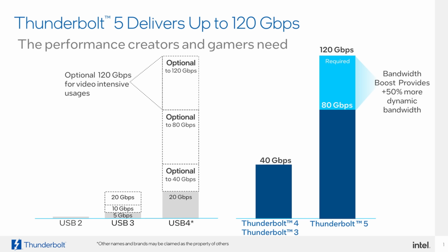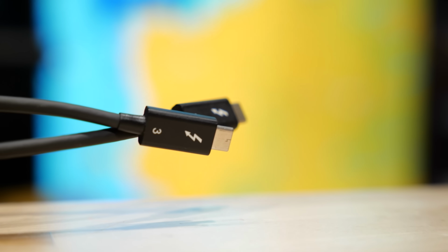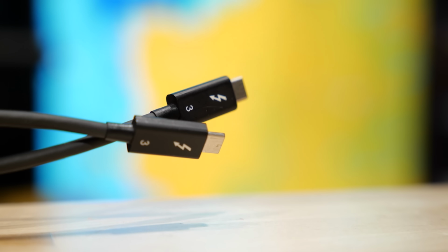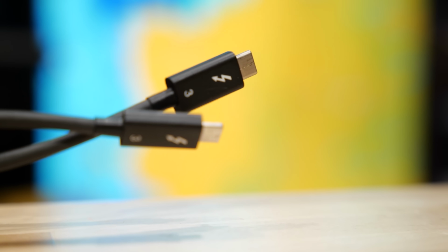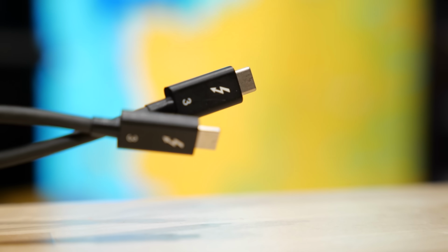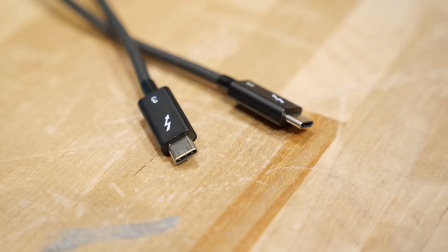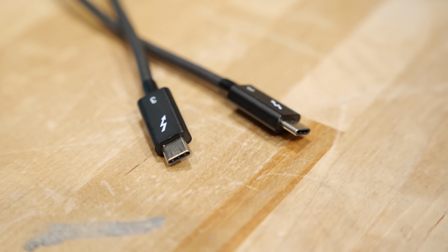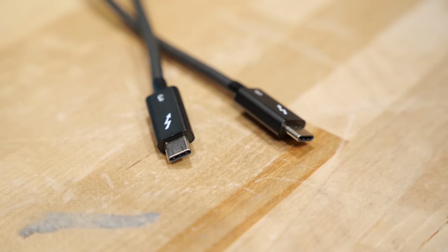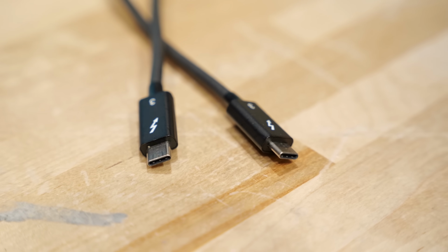What most people don't realize is that these Type-C cables, the reason they're reversible is because the top and bottom half of the cable actually has the same connections. And so when you plug it in and then you plug in the other side, it doesn't matter because there's two sets of connections there. You may have seen like 20 gigabit as 2x 10 gigabit on the USB side of things. And that's simply just two USB connections in one end.